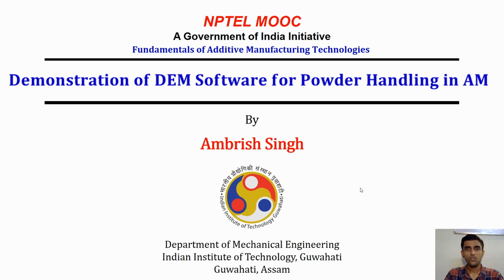As we now already know, there are several additive manufacturing processes that use powder form of feedstock material. These include binder-based additive manufacturing, powder feed-based additive manufacturing, and powder bed-based additive manufacturing. Thus, it becomes imperative that we understand the behavior of bulk materials, that means the behavior of granular materials. The fundamental understanding of granular materials can help us in designing efficient additive manufacturing machine tools.